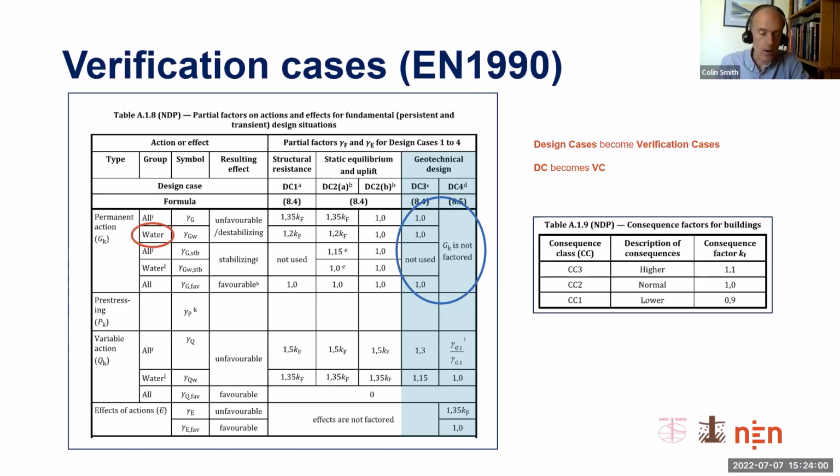It's good to see that we have specific mention of water. There's been a lot of debate about how to deal with water, and how to deal with that very well in geotechnical analysis and design. I think it's acknowledged that generally you don't want to be factoring water pressures and then feeding them into effective stress analysis. That just doesn't generally work very well, if at all satisfactorily. So here it is clear that we factor water pressures with a factor of 1.